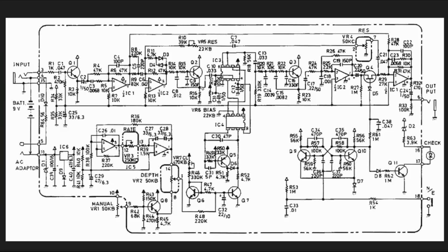Okay, if you remember from the CE2 video, the Boss used a compander before the input to the BBD devices to make sure that we are limiting the dynamic range. Here, however, that dynamic range limiting is being done by way of these diodes in series with this resistor. Putting the resistor in series means that we're not going to really clip so much as we are going to limit the signal. And these values have been chosen specifically to work together to limit the signal to an appropriate voltage.